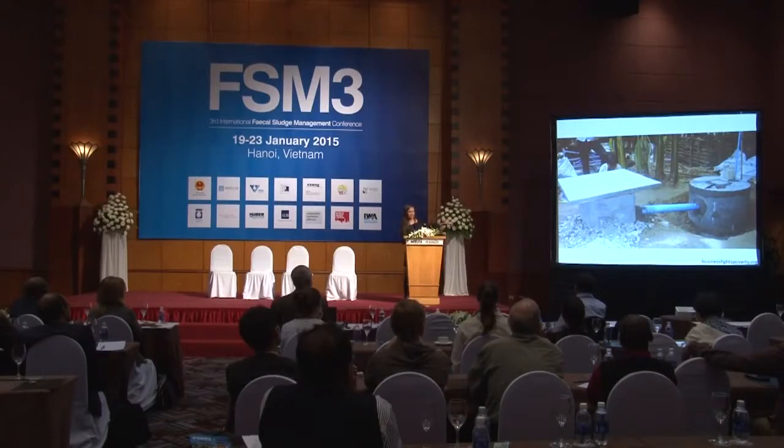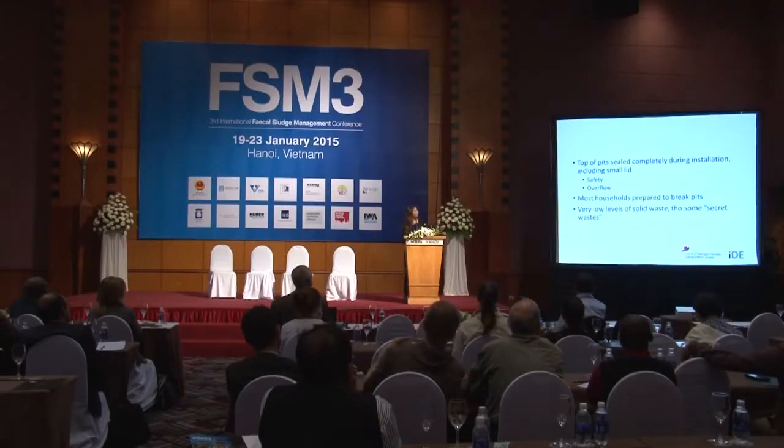12. Some of the other things that became apparent during the study: the tops of the pits are sealed completely during installation, including the very small cover on the top of the pit, which should in theory be left unsealed to allow for emptying. You can see in the picture that during installation everything is sealed with mortar. This is mainly because of safety concerns.